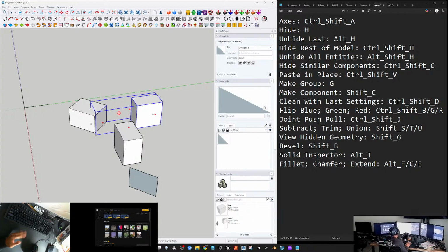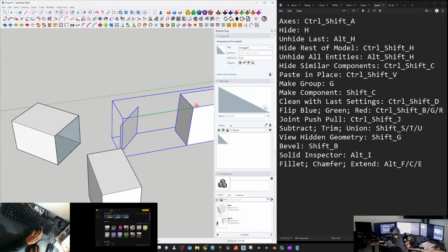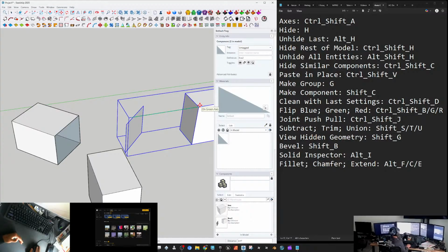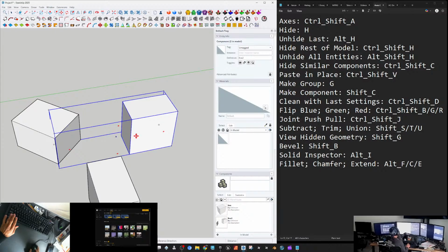Let's say you have an array of objects that are repeating across a wall, like some light fixtures that are equally spaced. And let's say you want a light fixture to be exactly 5 feet away from each door in your scene. Instead of moving the light fixture by one of its corners and then trying to calculate the distance from each door, I can grab that light fixture.